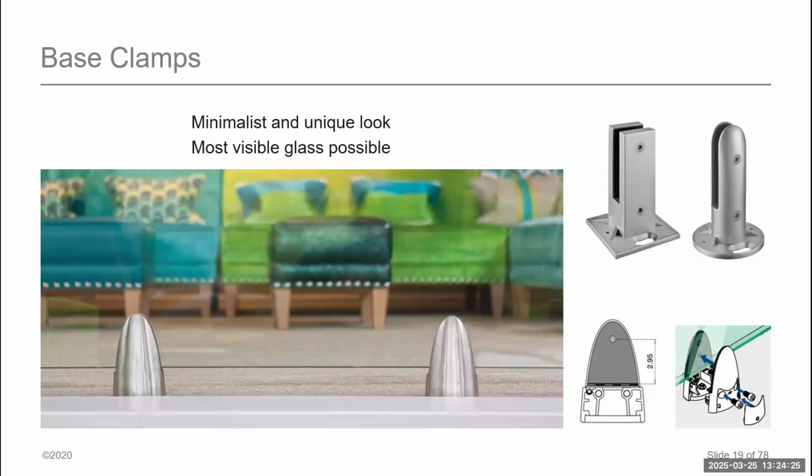Now, what does that mean for us? It means a few things in the design stage. Typically, you will see a lot of prescriptive engineering out there for base shoe systems because we do have predictability in the performance of the shoe leg resistance and the glass itself. So you are most likely able to prescriptively design and engineer a base shoe system.